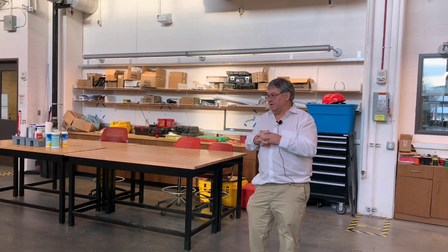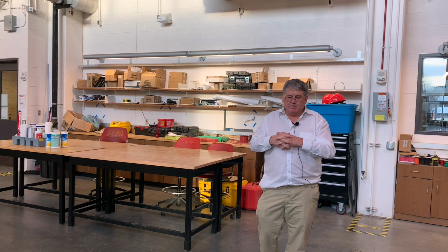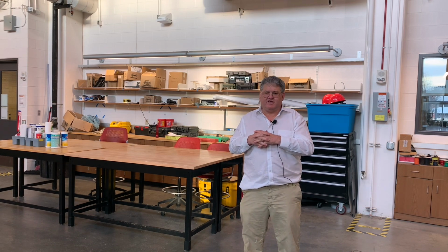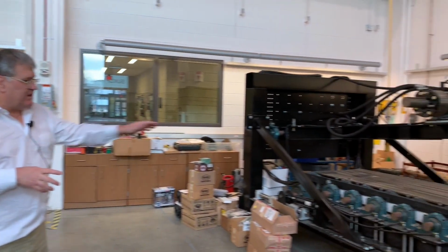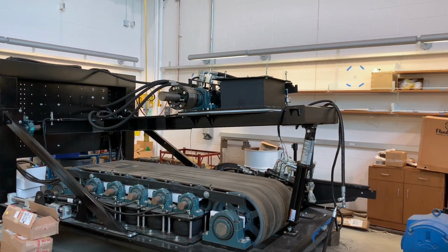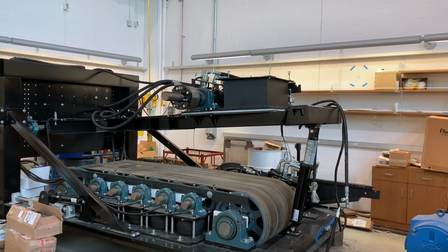So the other two pieces of equipment that we've been developing over the last 2 years are a very large vehicle dynamometer out at the agricultural research farm. Essentially that is a machine that we will be able to test tractors on from up to 650 kilowatts. This is just a single tire tester. So in this case, we have a belt that can, again, put a load on a single tire, where the tire could be driving the belt or the belt could be driving the tire.